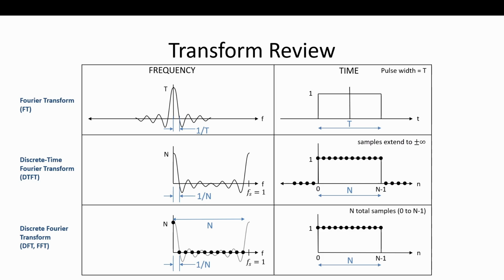Is that clear? So that's what happened. All we did was sample it. We got this periodicity, and I'm just showing you from 0 to Fs. Why? Because if we kept going, you'd just see the same thing again and again and again. And the point is that it's still n samples. We still have the null at 1 over n, and it's going to infinity.